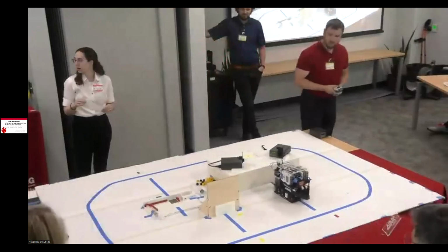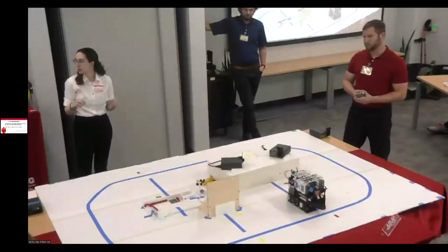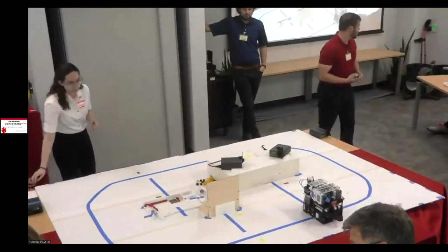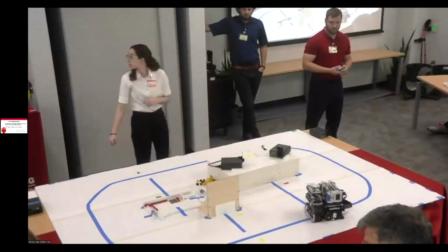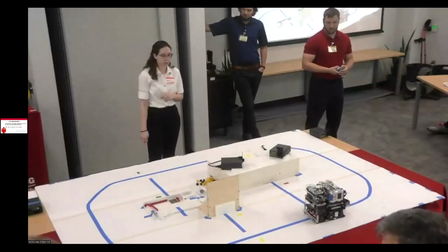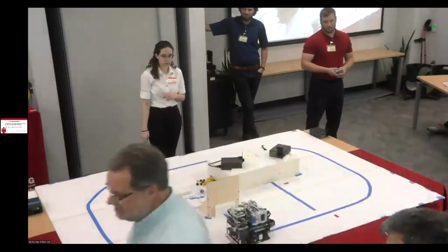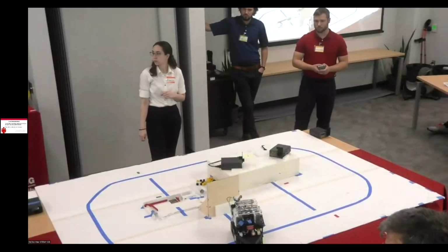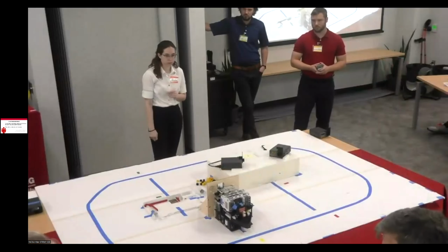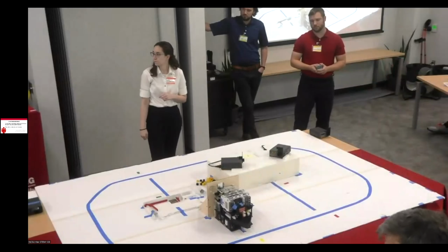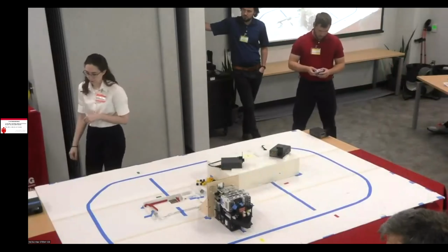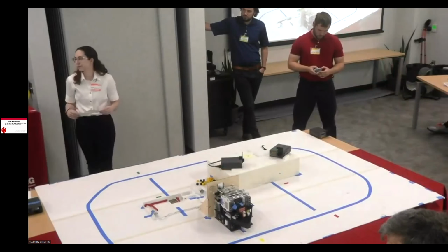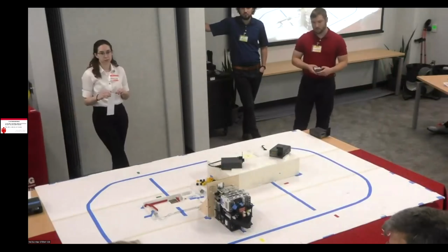Motion. So what happens with that, the front and rear wheels are the omnidirectional wheels, they allow it to move in 2 directions freely. When those wheels hit the dowel rod, it pops up onto it slightly, but doesn't quite go over because of weight distribution. We didn't have an accurate weight distribution when we were testing, so we didn't see this issue. But when those front wheels hit the dowel rod, it picks up the whole AGV from that front end a little bit and takes enough pressure off our drive wheels where they don't have enough traction to keep pushing over. So when did you recognize that problem?